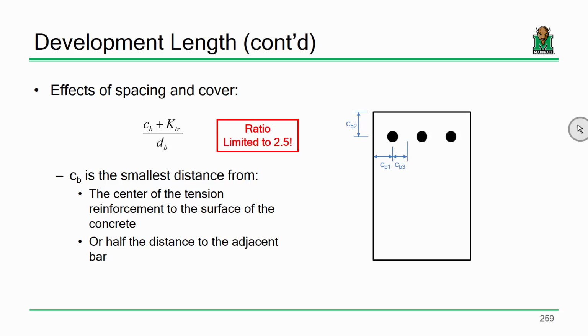For typical scenarios, you're right that there are probably some typical standard values that you're always going to see. But it's engineering. There's always something complicated. I guess the same could be said for DB2. Usually it's about 3. You are right. Most of what we've done for our beam design problems is we've said the difference between D and H for our purposes has always been 3 inches. So you're exactly right. Make sense?